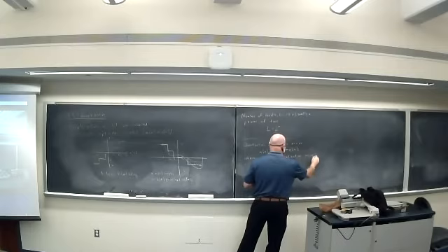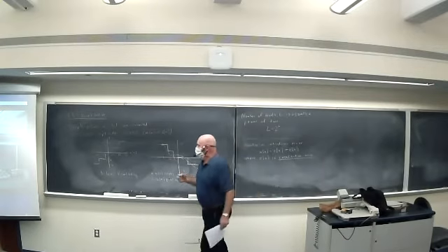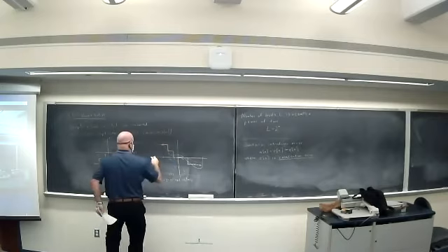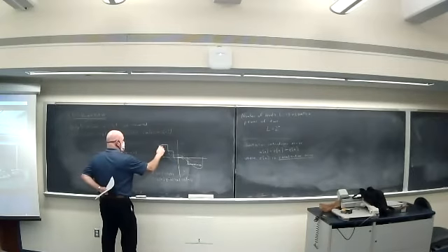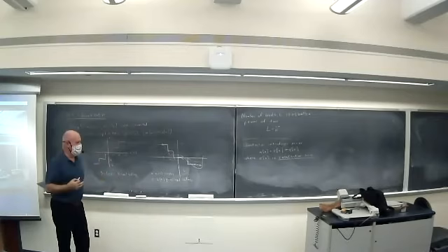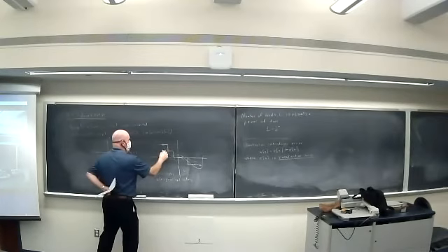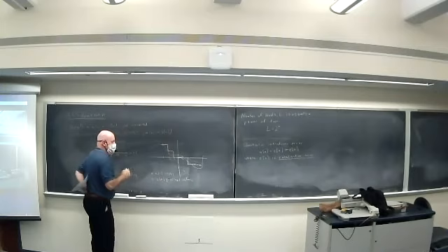Sometimes quantization error, but often quantization noise. It's exactly as if at each sample point there were noise present on top of the waveform I'm interested in that caused errors in my sampling.